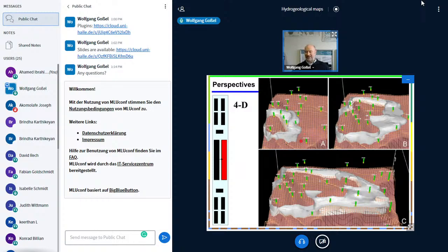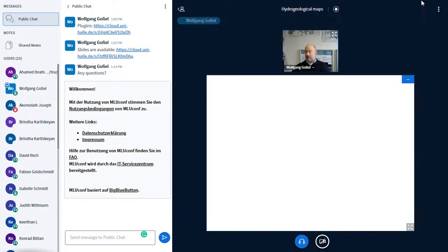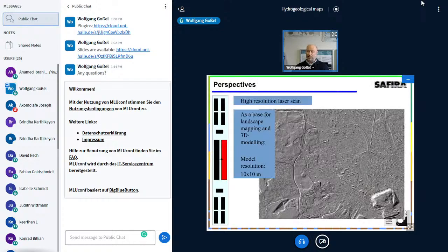Here you see 4D, in this case only 3 pictures from different time steps, and you see how, for instance, this contamination plume develops over time. This is quite helpful to see: during this time I cannot measure any contamination at this point, but after this time I will measure the first contaminants, and here I measure very high concentrations. So this is very, very helpful. In this Bitterfeld area, it's especially important for the beavers, because by now they get dioxin and they get poisons, and this is not the best idea for nature reserves, that the animals get poisoned there, poisoned groundwater.